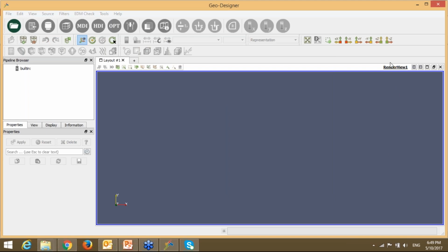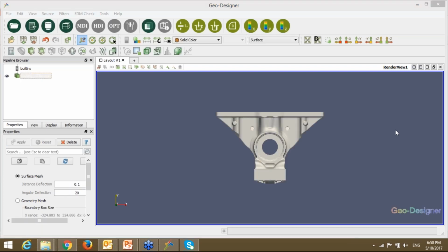Okay, one more question is there. Is there any effect of the core part in the actual hotspot section? No. Basically, the core is in touch or in connection with the casting part, or even the sand mold is in connection with the casting part. But what we are analyzing here is the pattern of solidification. That pattern of solidification will solidify irrespective of the core location or irrespective of the sand which is in connection with the casting part.